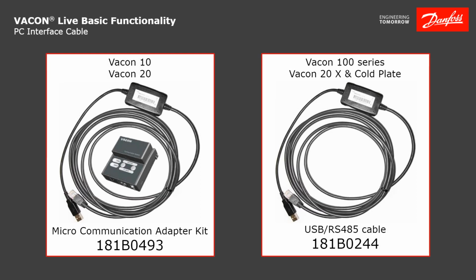The PC interface cable for the VACON 10, 20, and 100 series are all the same. The VACON 10 and standard VACON 20 do use a micro communication adapter, so you would want to use the part number 181B0493 micro communication adapter kit, which will give you the cable as well as the micro communication adapter that will fit onto the drive. If you have a VACON 100 or a VACON 20X or VACON 20 cold plate, you can order part number 181B0244, and that would just be the cable only.